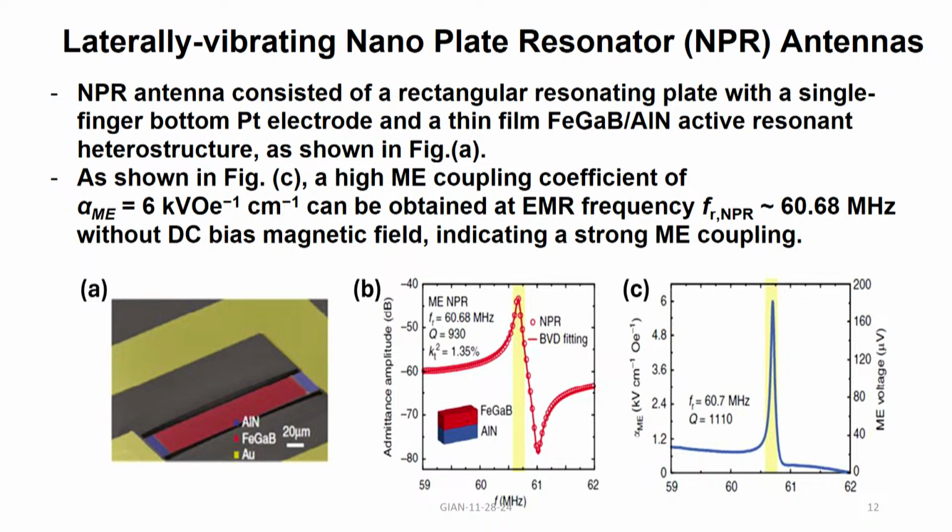That is what happens when you shrink the length from several millimeters to hundreds of micrometers, and the resonance has very high Q. That is what you want a frequency selective antenna to be. If the Q is very poor, then the antenna selectivity for frequency is very poor. Okay? It is spread out. This resonance will look rather wide, and so the frequency selectivity becomes rather poor.